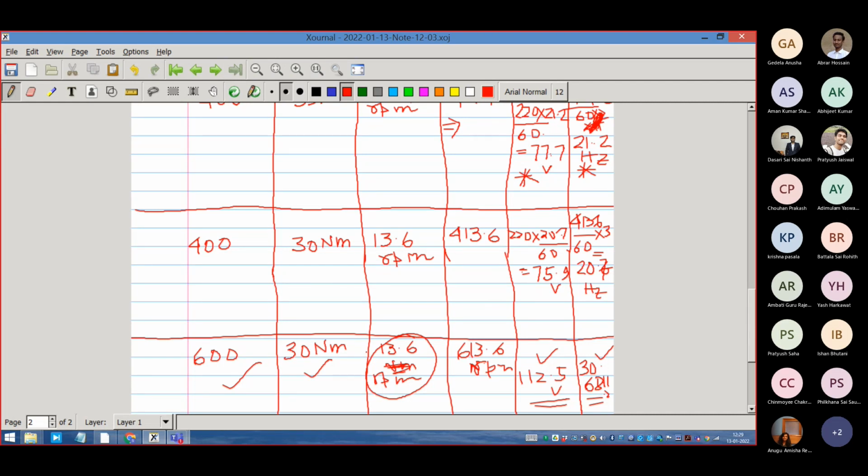If you do any kind of induction machine control, this is the essential objective. There are various ways of arriving at it. Some people call it vector control, some people call it direct torque control, but none of them will violate it. Okay, the simplest possible way of achieving it is called the V by F control, right?